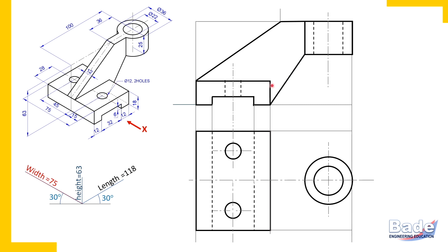So this is how we have completed the plate. Now draw end projectors of this plate. Watch this plate in the front view. Extreme right of the plate and extreme left of the plate. From these two extreme points, corners of the plate, we should draw projectors. These are called end projectors. And this is how we have completed.